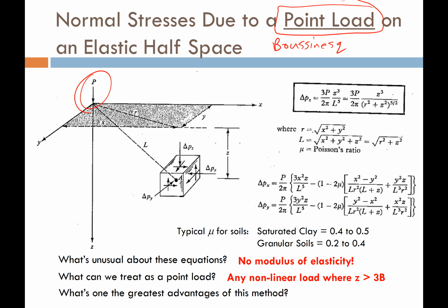What's one of the greatest advantages of this method? Well, one of the things we like about elastic methods is that we can apply the principle of superposition, meaning we can take a complex load, break it up into a whole bunch of individual loads, compute the response from each one of those loads, and simply add them together.